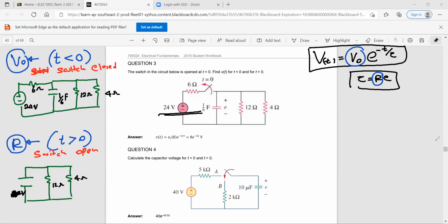Now let's see what is happening. What do we mean by V naught, guys? I gave you the definition. V naught is the voltage when the time is equal to 0. When the time is 0, what is happening? The capacitor will be fully charged, so this will act as an open circuit. Do you agree, guys? When the time is 0, this circuit will become an open circuit. Do you agree? Yes, and then for time more than 0, it begins discharging.